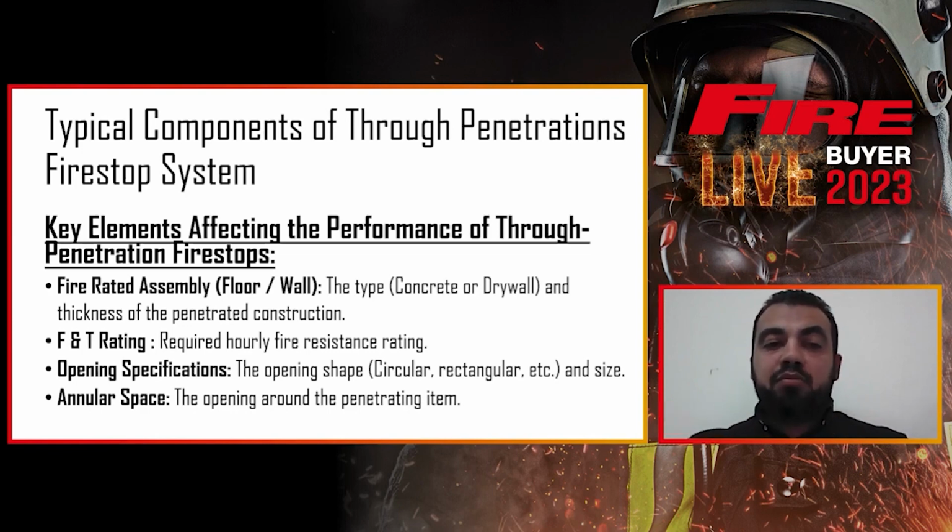Second point, we have the F rating and T rating. What is the F rating and T rating of the fire-rated assembly? When you are selecting your system, it should match the fire rating. This is mandatory for all systems, and there are some exceptions for the T rating.